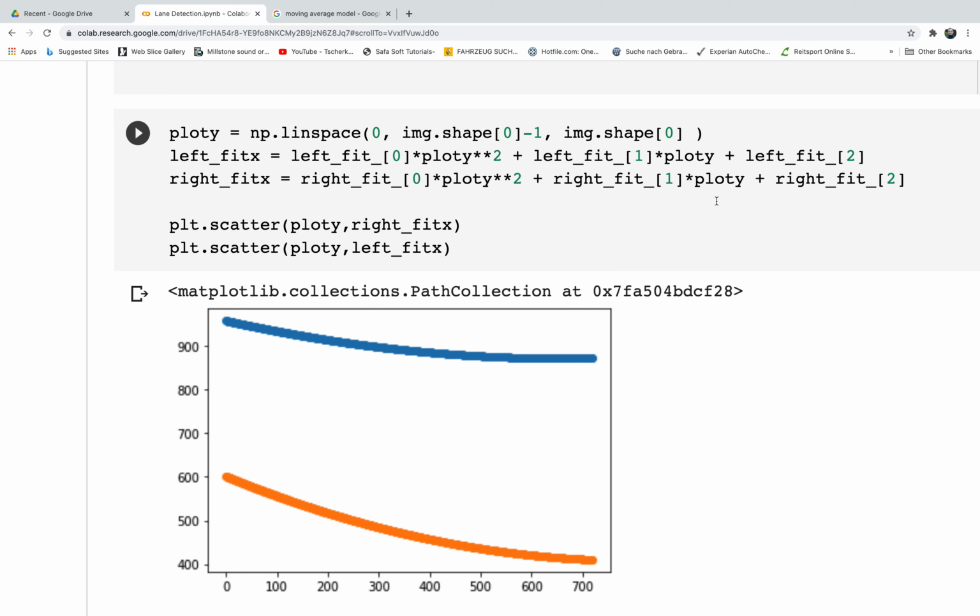Now, with that, I'm storing the control input, so I'm storing how the autopilot of Carla is giving actions, like for example the lateral actions, mainly steering left or right. Just remember, Carla is relying on the waypoint, which means a pre-planned path. So it knows the path. It doesn't depend on vision like we do here. It does know the path already. So that one is following the correct path, and we are estimating the lanes using vision.